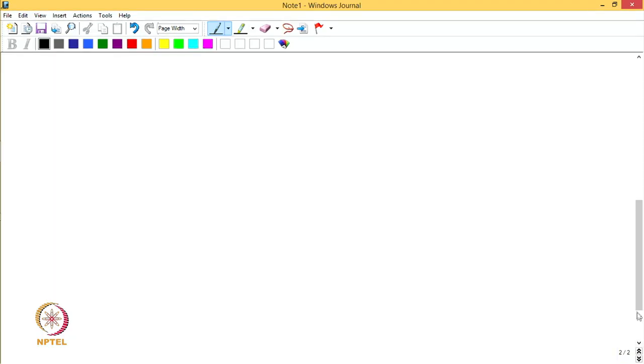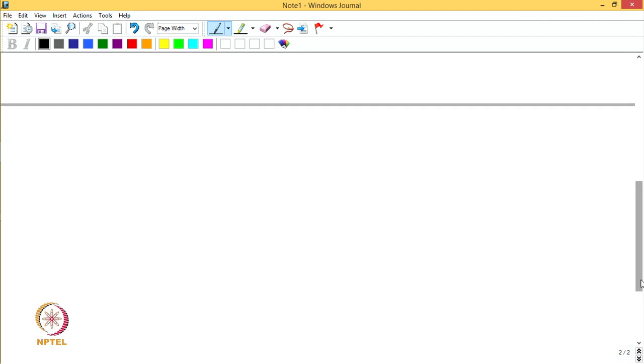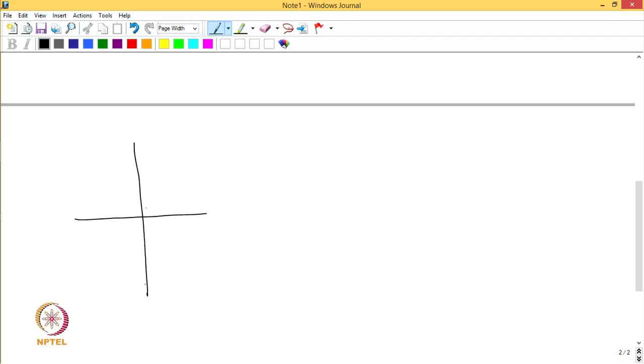Alright, so let us begin today's lecture. So far we have looked at superposition of elementary flows, and the kind of flows that we have looked at, just to bring your attention to them again: we looked at how when we superpose a source and a sink which are very near each other, and near the origin, we could derive a doublet. So, we got a doublet out of this superposition.